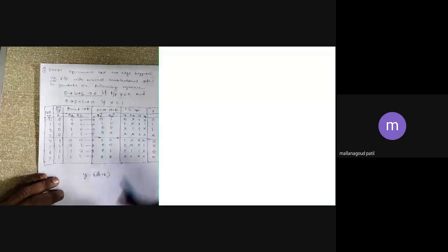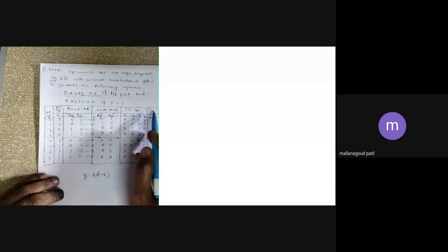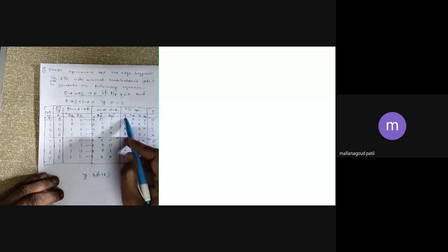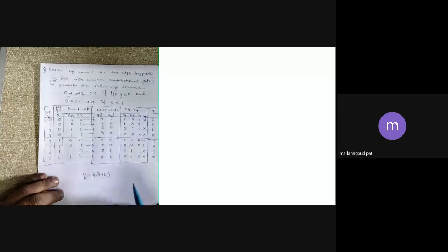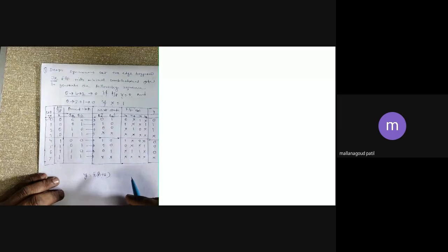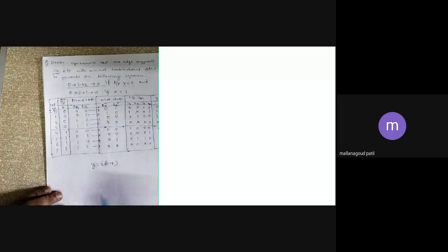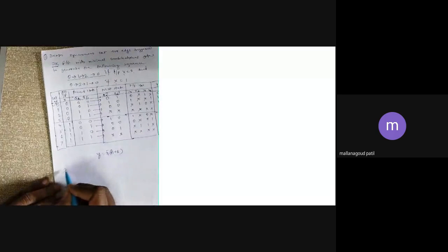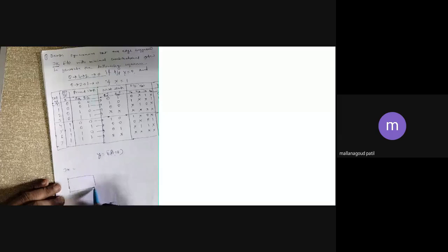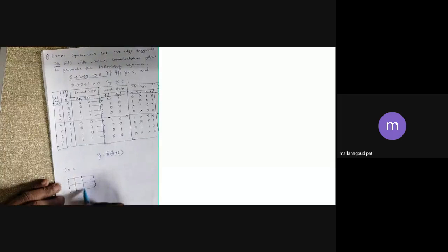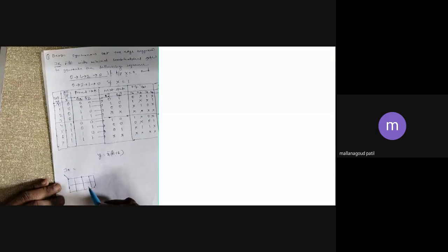Then what should you do? Taking the flip-flop outputs and the final output, you have JA, KA, JB, KB to put into the K-map cells. When you put them into the K-map cell, immediately I can do the next. What is JA? At least see the procedure and you will come to know that. I can write this is my X and this is QA, QB.